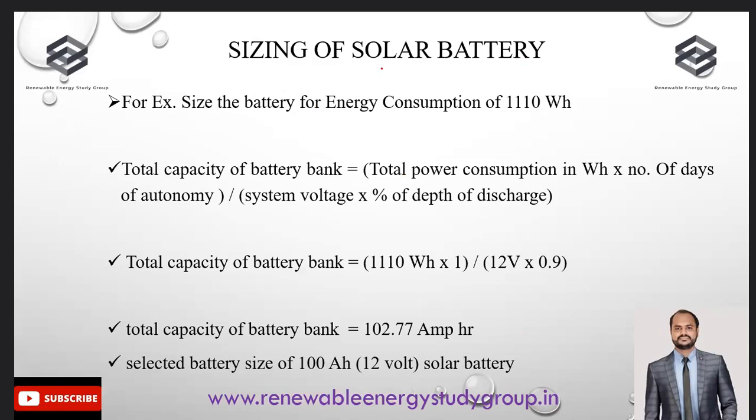Once we have designed this, then we have to calculate the sizing of the battery also, because this is the upgraded kind of system when we talk about the DC load system. In that case, we must calculate how much battery backup will be required as per the problem statement. The size of the battery bank depends upon the regular consumption of the consumer. As per the initial calculation, we have calculated 1110 watt hour. This will be the consumption of the consumer. So we just consider this consumption and we can use this formula.